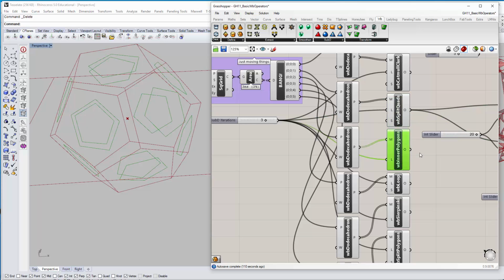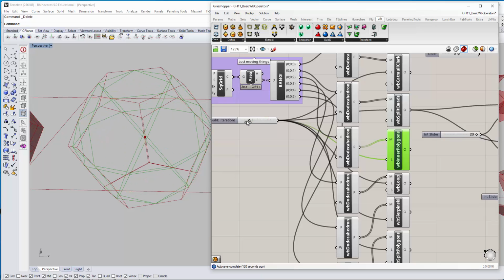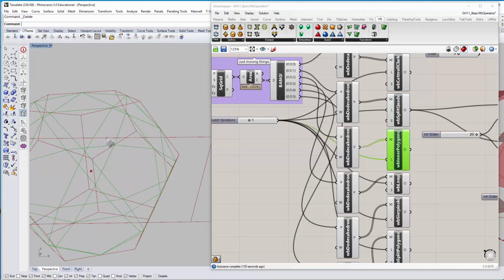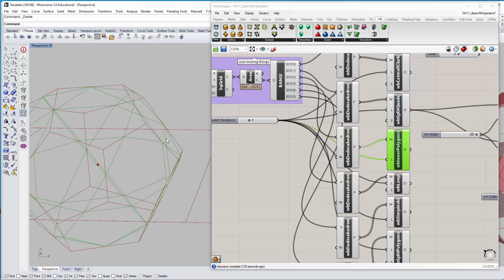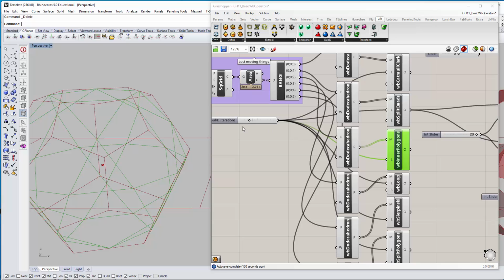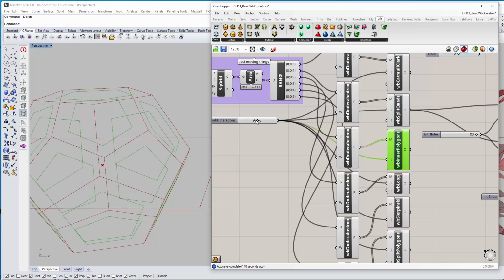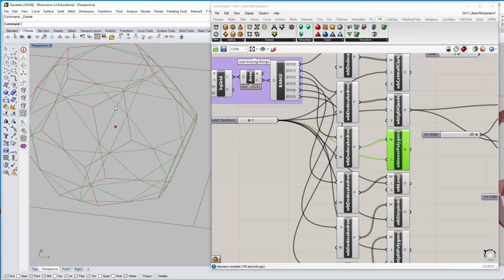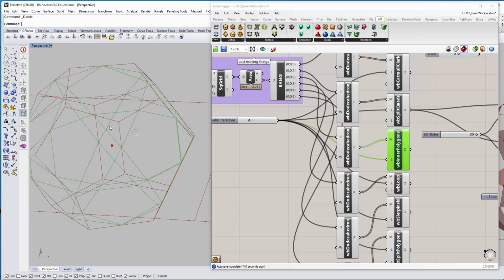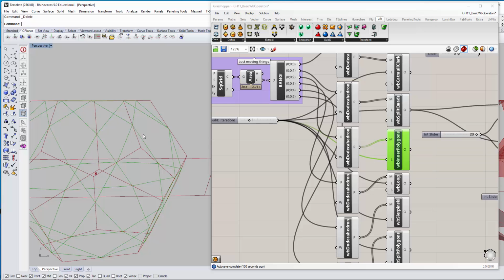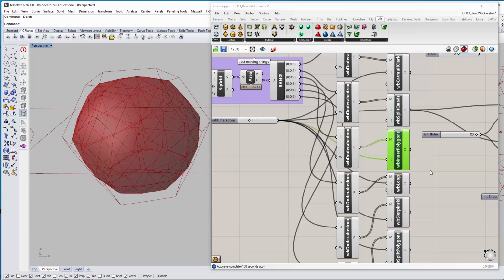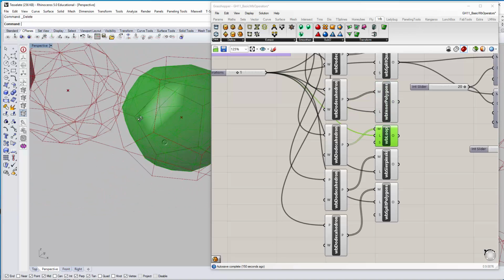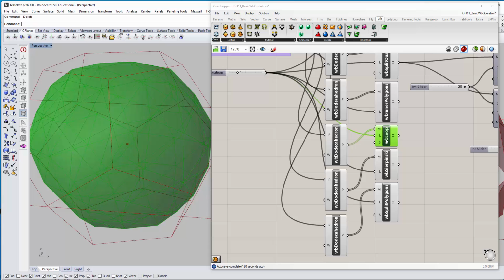This is the inner loop or inner polygons subdivision. So go back. So this is basically using the midpoints to redraw a series of polygons, and each loop successively gets smaller and smaller. Right? If I baked all 3, then they would all be circumscribing pentagons within each other. So it's really simple, easy to understand. Weaverbird's loop is one of the commonly used ones. WB loop is a very commonly used one.